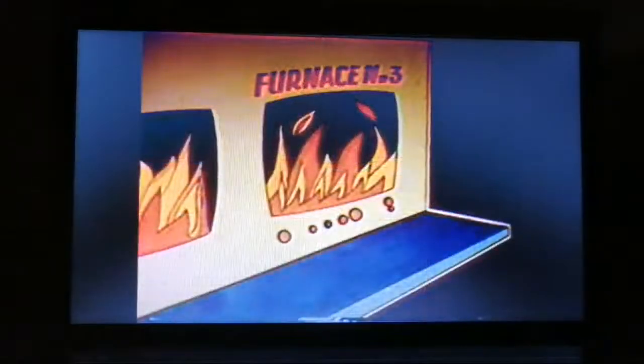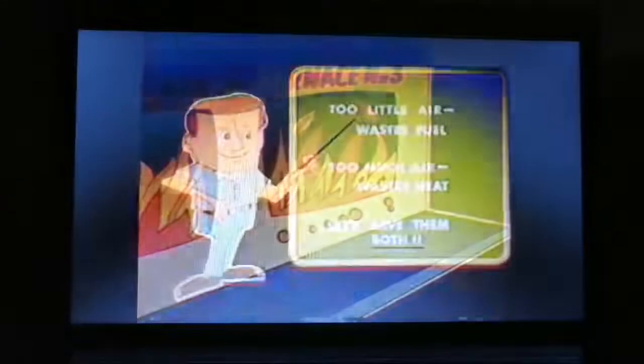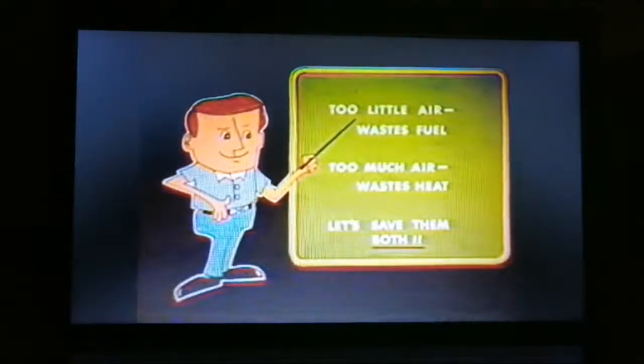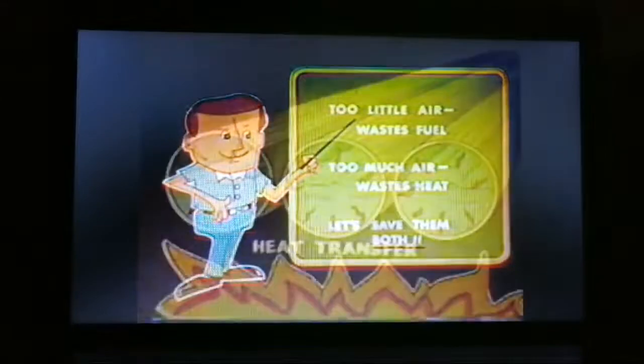Other devices may keep watch on the flame size and temperature using photocell devices which see flame temperatures by measuring ultraviolet or infrared light levels. Many units employ closed-circuit TV to observe flames within furnaces. Others use special detectors which warn the operator if the flame gets too large or too small. Correct, efficient combustion monitoring and control can easily save a plant several tons of fuel every hour.